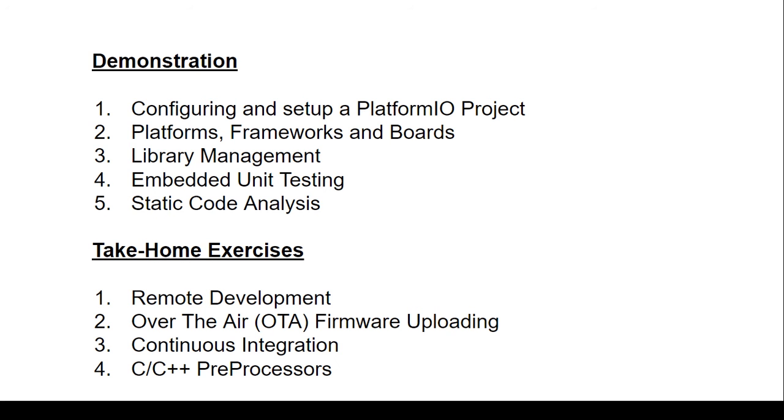But if you use the remote development tool provided by PlatformIO, you can ask the friend who has access to the hardware component to run this remote development mode on his computer and connect the device. Then you can remotely connect to that device, write some programs, upload them and see the output of the device. So this can be a very useful tool for you.